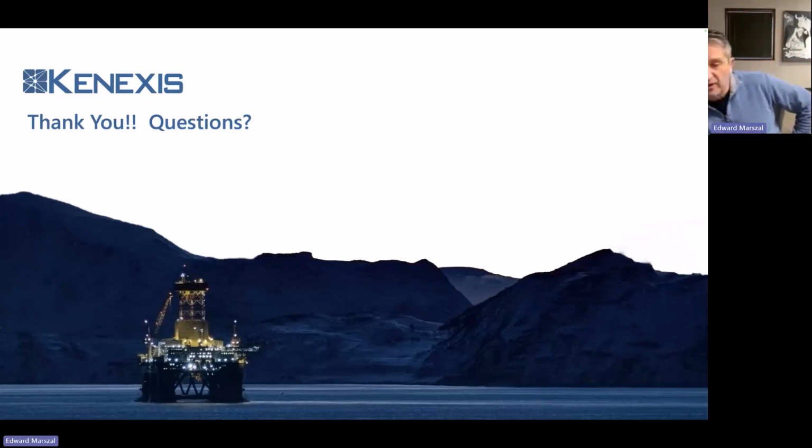Okay. Let me get to that question. In your case, if we're talking about thousands of loops, the way I had it set up is I had one file for the entire commissioning process. You might want to break it down into multiple files. So you might have one Open-PHA checklist file for each piece of equipment. And then you can assign those pieces of equipment to different technicians and have them check in on a regular basis. So instead of just one study, you would have multiple studies. That's one way to do it.